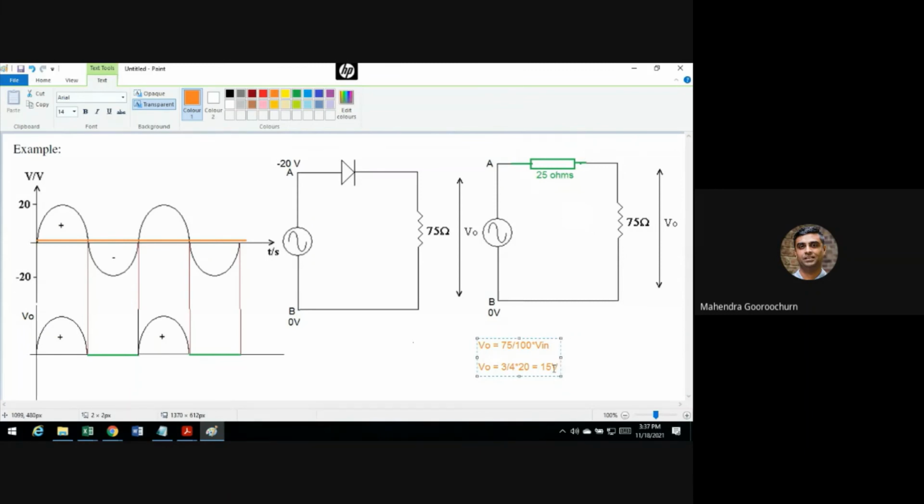So the remaining 5 volts that you find there would be appearing across this diode because it has a resistance. Yep. So two implications of a real diode. First, you need to have at least 0.3 volts to start conducting. So you have a small segment there where it's going to be flat. So then your graph will start picking up somewhere there.